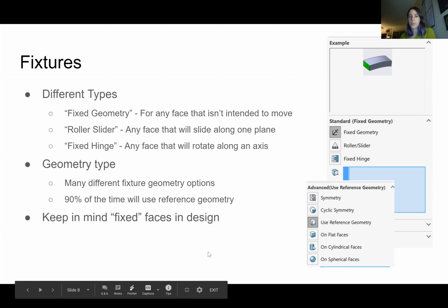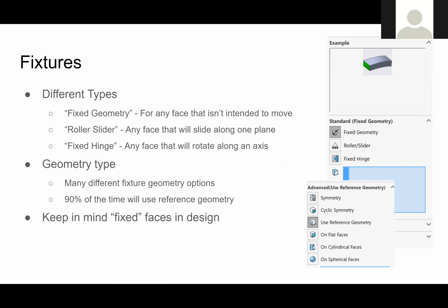One of the basic things you're going to work with when doing FEA is, before you start, you want to set up your fixtures. These are defined as basically the mechanical and physical constraints or constants that exist in your system. Most commonly, you just use fixed geometry. You just say, this thing is going to be glued, or bolted, or very securely attached. I'm going to assume that it's unable to move in space. You can see that in the green face that's highlighted on the right. It's been fixed, and the rest of the part is free to move, but that face will never move or